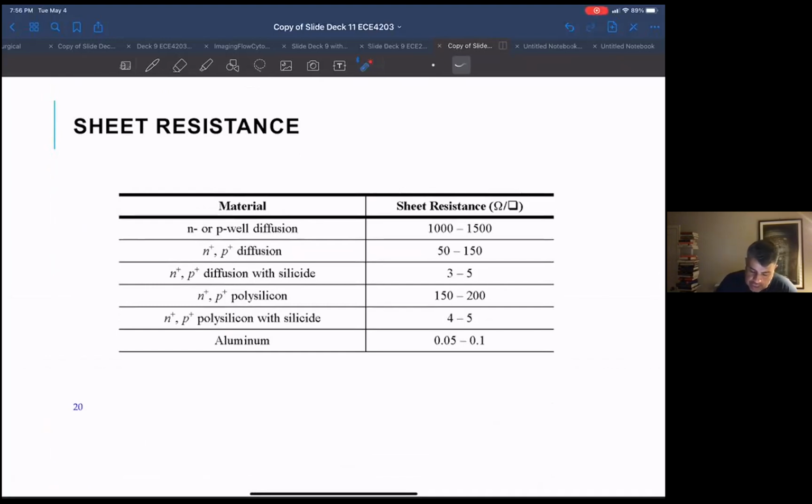And again, the key thing I want you guys to take from this is that, whether you've got aluminum or copper, you have a certain resistance in the 0.1, 0.05 ohms per square range. But you will be tempted, if you're doing chip design, to start routing things in poly, or even at some point you go, well, my N plus diffusions are conductive, I'm just going to route this drain to this drain of two transistors that are not sitting next to each other.